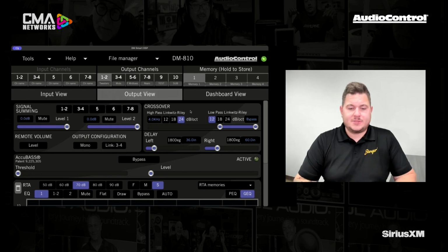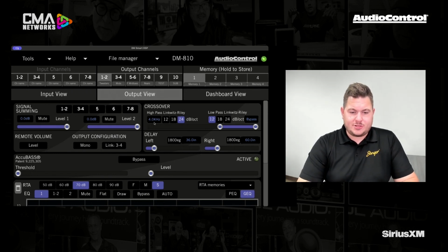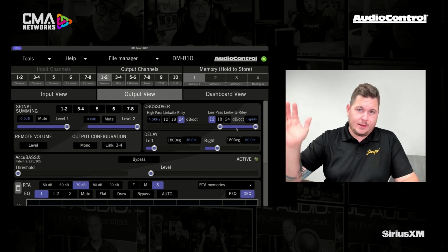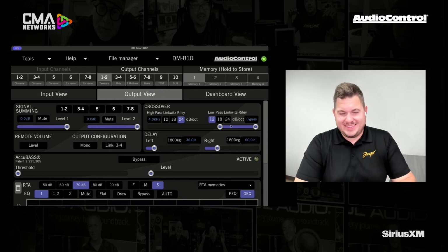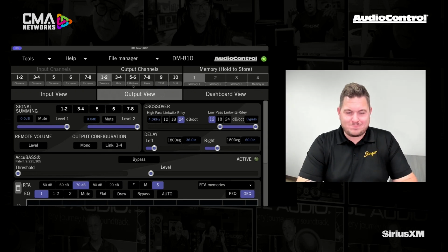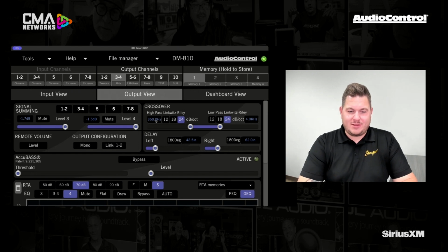and our products. So you'll notice that the tweeters are crossed over at 4K with a high pass crossover. So we have them set at 4K on up. So they're going to play from 4,000 hertz on up to infinity, right? So when we look at the mid-range channels, we can click on 3-4. Those are set from 350 hertz to 4K. The front mid basses are set from 350 down to 80.